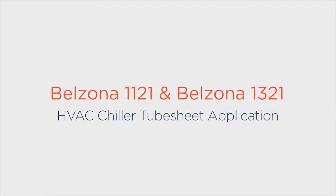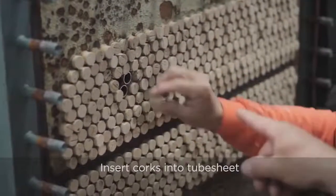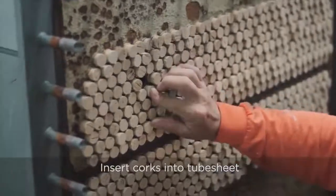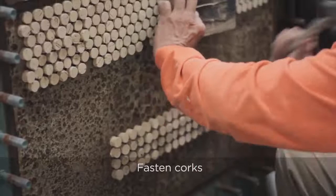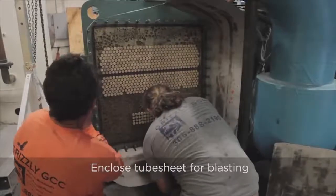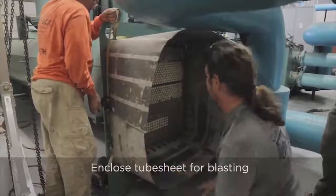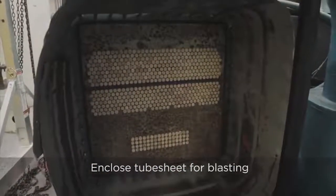Okay, so this is just a quick example of an application we did onto a chiller, a tube sheet application. The first step is always surface preparation. The first thing they're going to do is insert these corks into the tube sheet. What this does is it blocks up the tubes themselves. The whole reason we do that is because we don't want any of the grit from the grit blasting, or any product, going down the tubes because it would block them. And a blocked tube would again reduce the operational efficiency of the system.